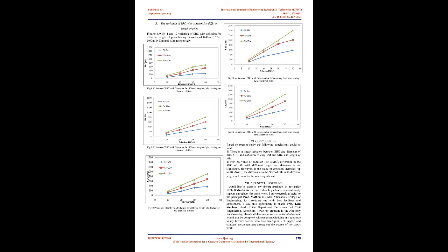Two, 50% of the final load at which the total displacement equals 10% of the pile diameter in case of uniform diameter piles. B. Piles of diameter more than 600 mm. One, 2/3 of final load at which the total displacement attains a value of 18 mm. Two, 50% of the final load at which the total displacement equals 10% of the pile diameter in case